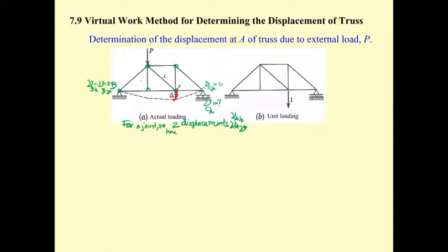So the structure under force here is actually going to move. If I were the analyzer, I would put this a little bit more and this a little bit less, and then the deformation of this truss is going to be something like this for the bottom chord. And for the top chord, since this one is down, it's going to be down, very close in the deformation. And this one is also down, and then the deformation here.